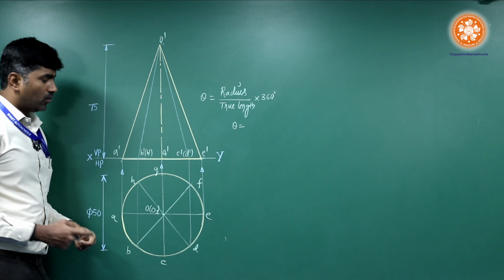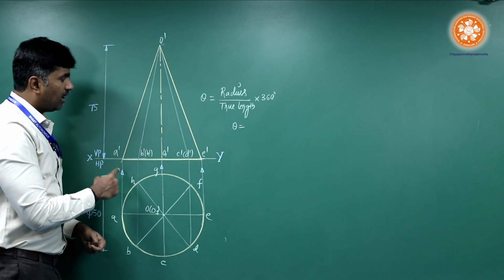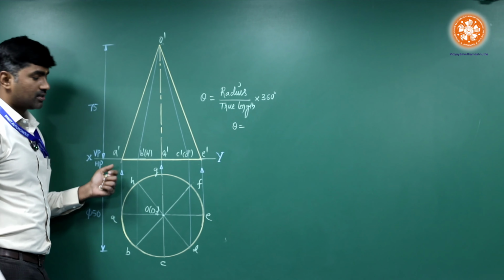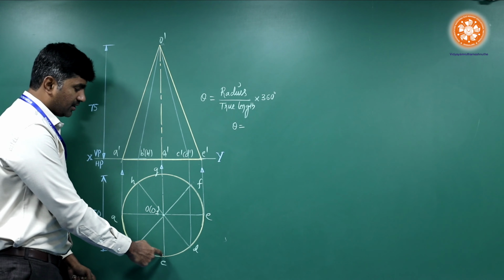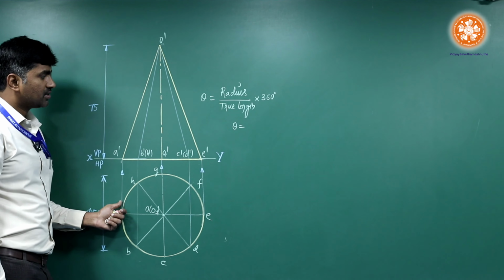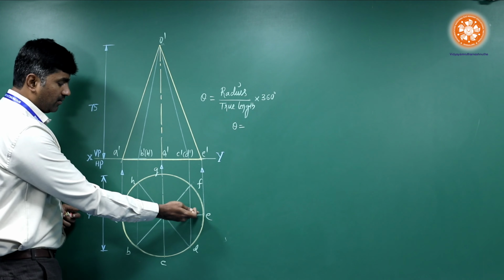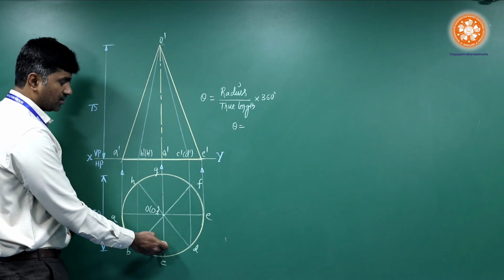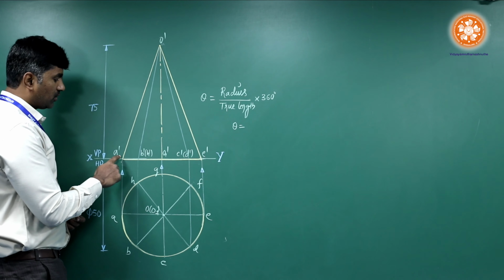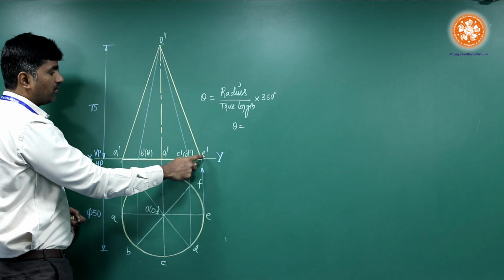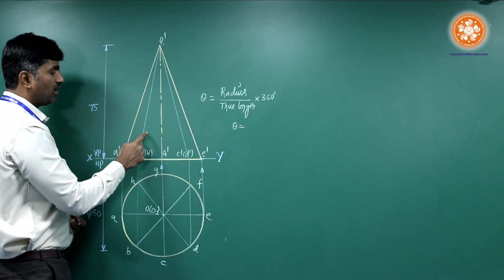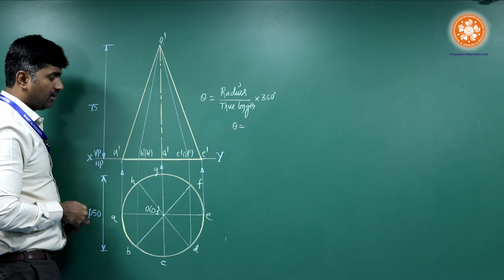The top view of a cone being just a circle and the front view being just a triangle, what we do is we just divide the circle into equal number of parts to show the namings. So we have considered 8 divisions and we have projected this accordingly. Make sure that the outer boundary of this front view should be a dark line and whichever is coming in between should be a thinner one.